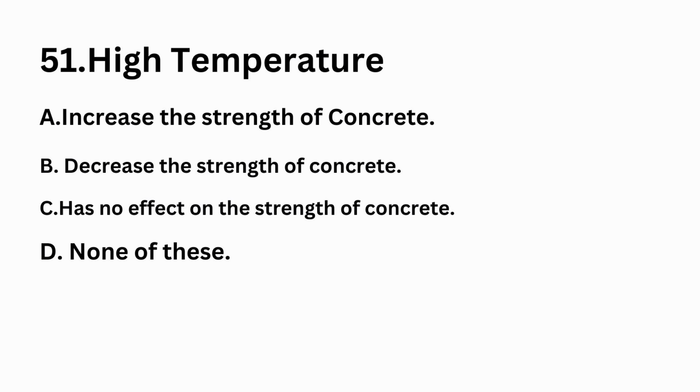51. High temperature: A. Increases the strength of concrete. B. Decreases the strength of concrete. C. Has no effect on strength of concrete. And D. None of these. A higher temperature of fresh concrete results in a more rapid hydration of cement and leads to reduced workability and accelerated setting. This reduces the handling time of the concrete. So the answer B is correct.